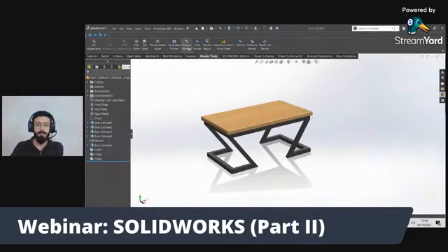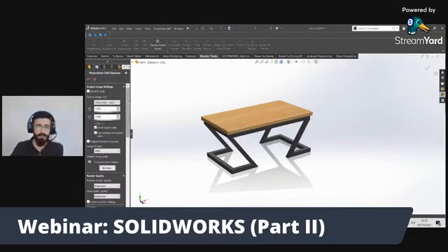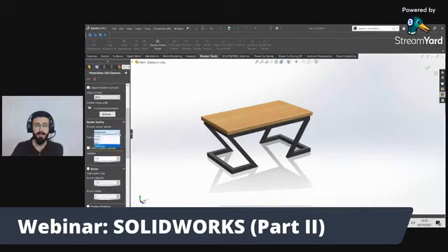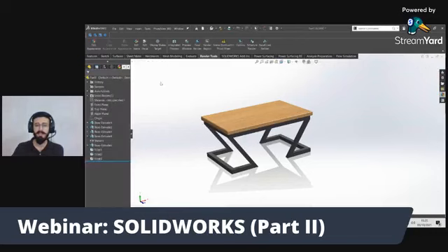And I want to tell you one thing: if you want to just make a render and save your time, there is an option here, render options, from where you can select the resolution. You can control the image format. Here are the image formats. There are a lot of image formats, and here you can select the quality. I have selected maximum. You can choose best, better, good. I have selected the maximum quality my CPU can support. From here you can change your rendering settings and all that.